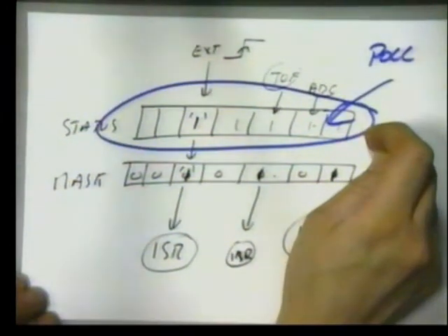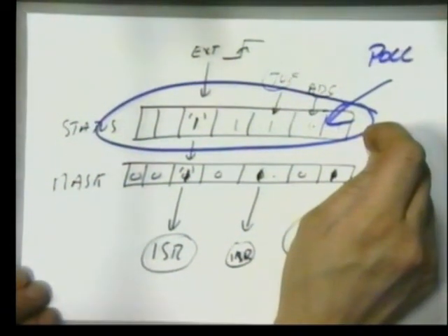Because all you need to do is poll the contents of the interrupt status register. That is dynamically telling us whenever an interrupt is pending. And instead of allowing the interrupt to occur in an unstructured, asynchronous manner, you can execute them in turn within your own background program whenever you want. So you've actually got the best of both worlds. The status register tells us if an interrupt has occurred.